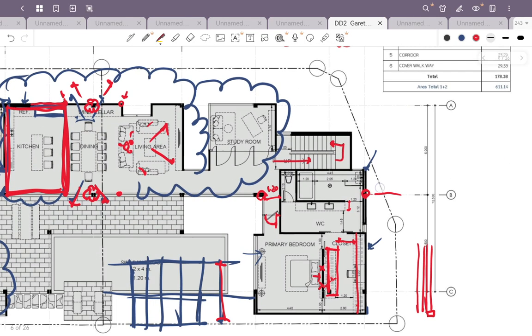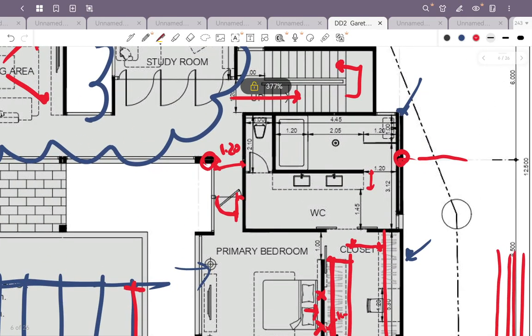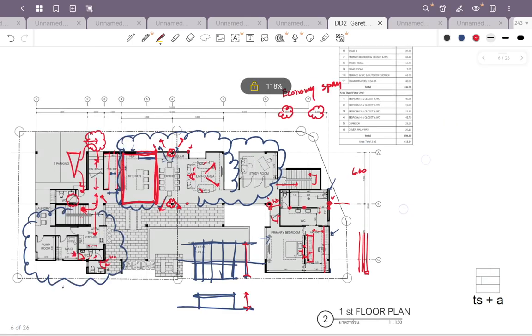We normally do 7 meters just for the car park or something where we don't want a column in the middle. But if they carefully place the column positions, they can have a column inside like this to make the column span less than 5 meters without affecting the function, and then you will save a lot of money on reinforced steel, because when the span goes over 6 meters, the reinforced steel needs to be changed to a different size. That means you will pay more, which is very unnecessary.